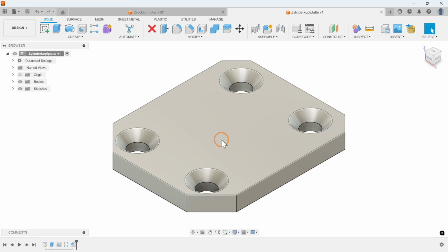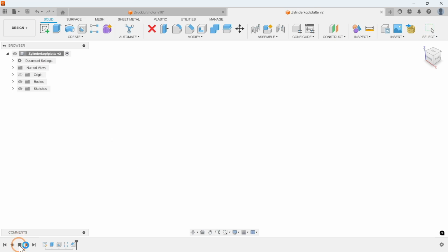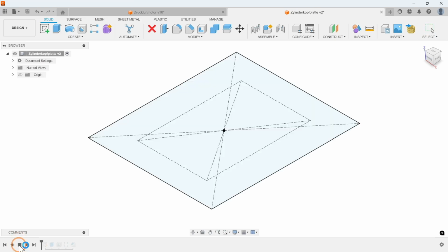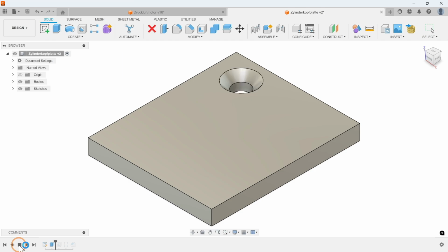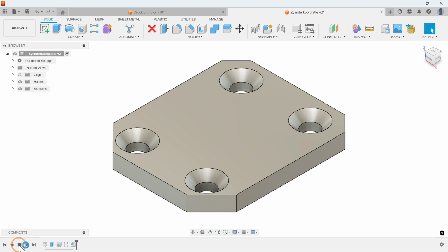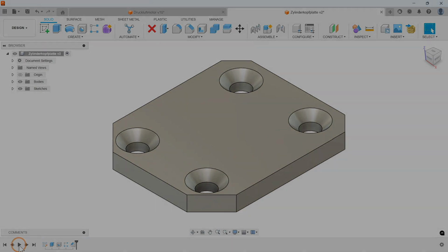Congratulations! You have successfully created the second component of our compressed air motor. You have the opportunity to review the entire construction process to understand all the steps precisely. First, you learned how to reuse sketches. Additionally, you learned how to create and arrange holes without a prior sketch. Creating multiple chamfers in one step is now familiar to you, and you know how to adjust the material of a component to display details such as mass, volume, and center of gravity. In the next video, we will focus on constructing rotationally symmetric components. Good luck with the next components.